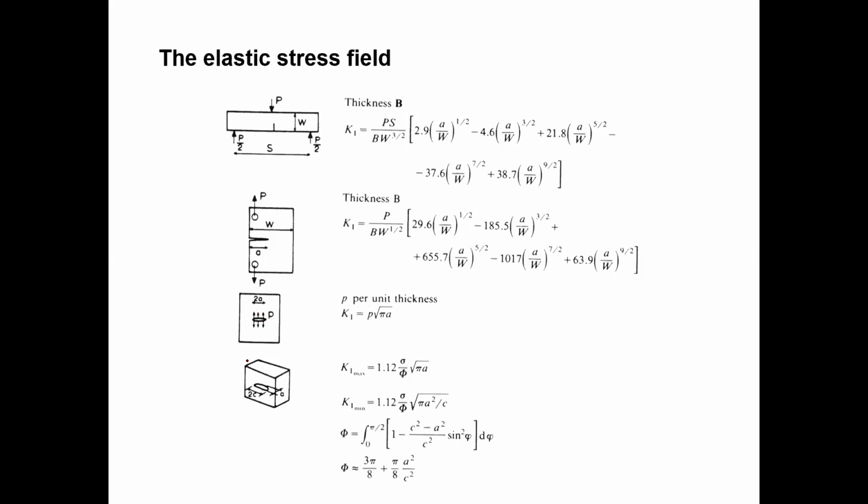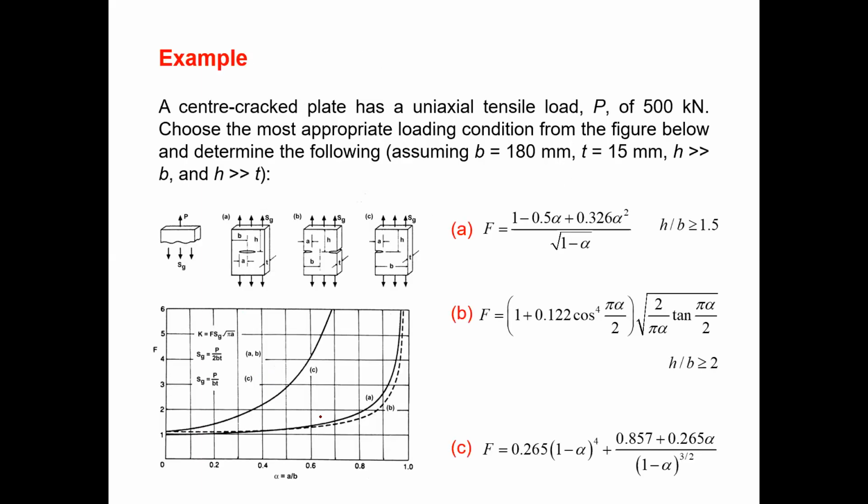And you can see this is not a homogeneous cross section; the cross section varies. So if you know the crack length and the diagonal diameters of the crack, you can use this equation to calculate the stress intensity. Likewise, with this example you can easily grasp that knowledge.